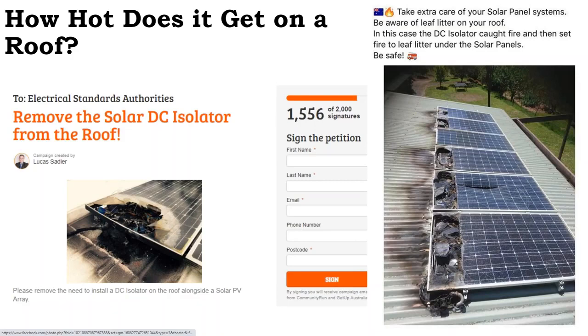Maybe not on record, but in your normal operating environment. You can assume the cold temperature side of things is going to be a little bit harsher. And generally, when you're looking at your temperature conditions, you're using the record low, but they let you get away with the ambient high because that hotter temperature, to some extent, is going to start dragging back your system performance.